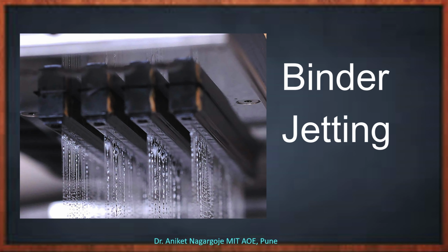Selective laser melting is a closely related process to DMLS. The laser completely melts the metal powder instead of sintering it, resulting in fully dense metal parts with superior material densities and mechanical properties. The next variant of powder bed fusion is binder jetting.